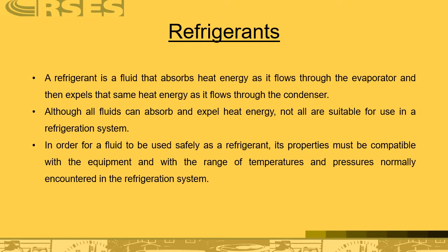Refrigerants. A refrigerant is a fluid that absorbs heat energy as it flows through the evaporator and then expels that same heat energy as it flows through the condenser. Although all fluids can absorb and expel heat energy, not all are suitable for use in a refrigeration system. In order for a fluid to be used safely as a refrigerant, its properties must be compatible with the equipment and with the range of temperatures and pressures normally encountered in that refrigeration system.